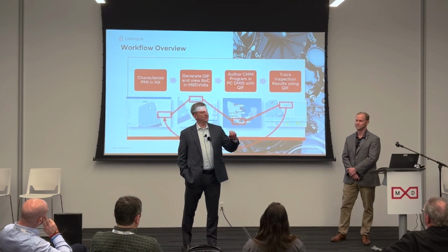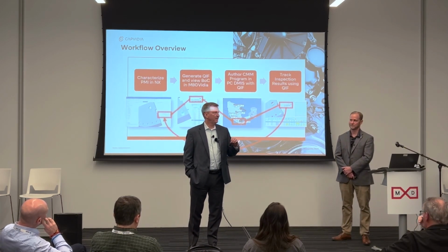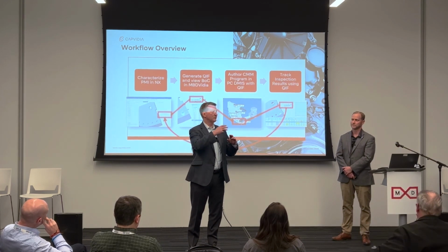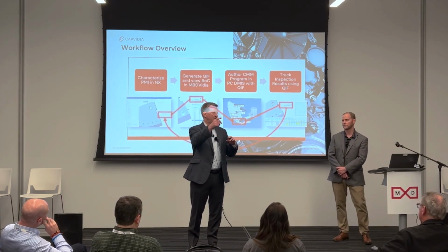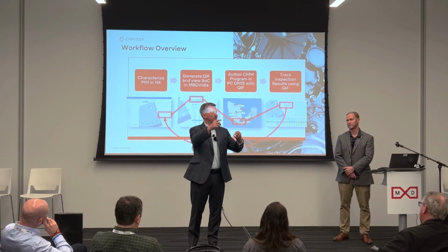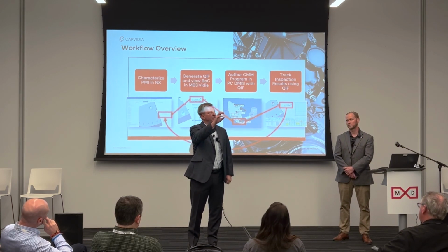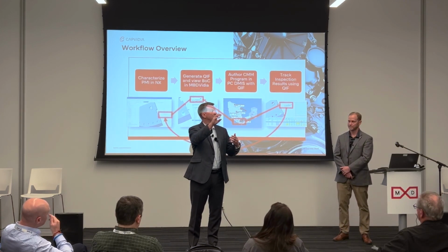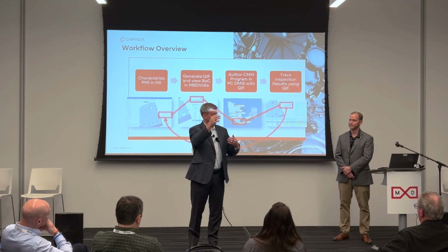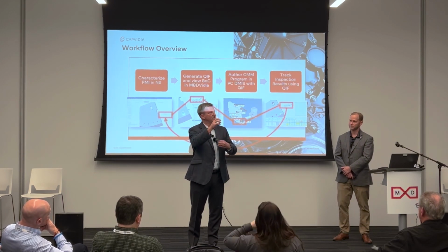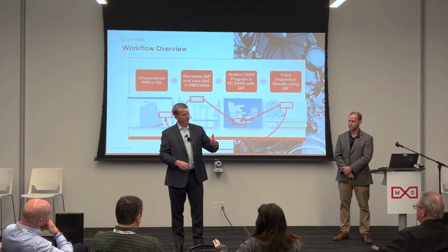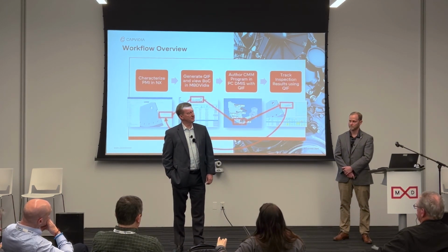The PMI is associated with geometry, and that geometry can be associatively updated, and the PMI will track to geometry. And if the PMI is tracked to geometry faces that disappear, the PMI are left hanging in space, and what NX does is tell the user that you had a PMI to a piece of geometry that's no longer there. Do you want to go ahead and delete it? Do you want to reassociate it to a new face? So if the face doesn't exist anymore, then the PMI doesn't know what to attach to.